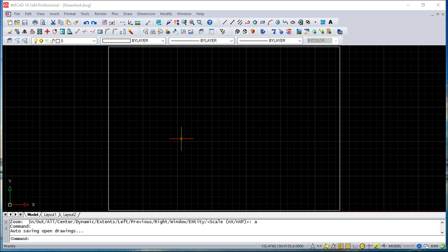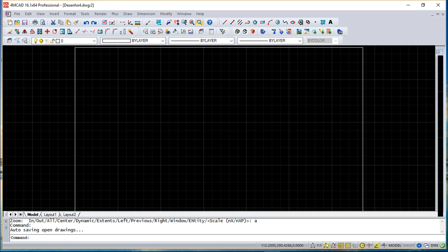But you can create other windows to display your elements in your drawing. So we can call these multiple views. And we can do this with several options and in several ways. So starting the first method to create a new window, it is coming to window menu and then new window.